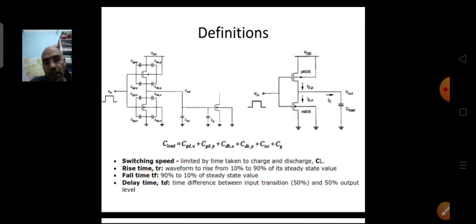That propagation delay comes because of the impedance. When we talk about impedance, it is basically R, L and C. But in this case, the amount of inductance is not very much. If you operate the circuit at very high frequency, there will be some inductance, but that can be ignored at the operable frequencies. So we only talk about the capacitance.